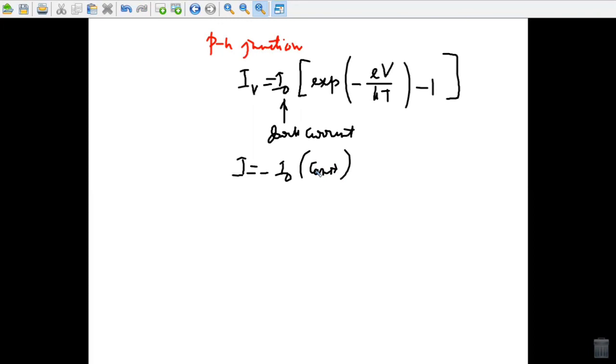So, as a reminder, or as a mnemonic: an N-type semiconductor is a semiconductor containing donor impurities, which can donate electrons to the conduction band by thermal excitation. The majority carriers are electrons. A P-type semiconductor is a semiconductor containing acceptor impurities, which can accommodate electrons that have been thermally excited from the full valence band into local levels. The resulting holes in the valence band are the majority carriers.